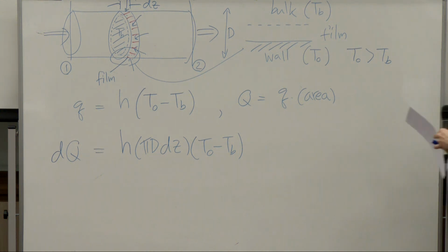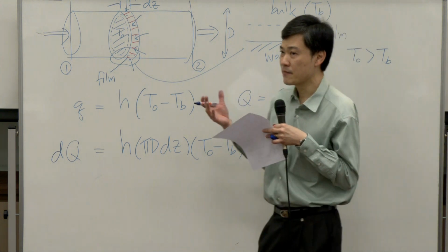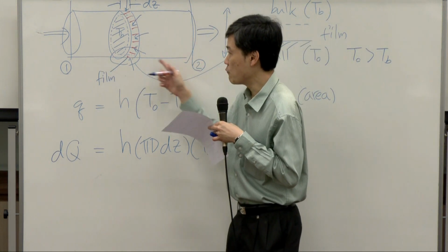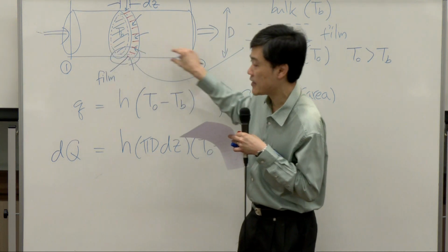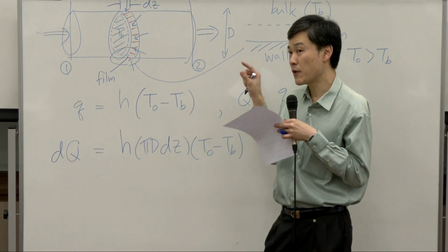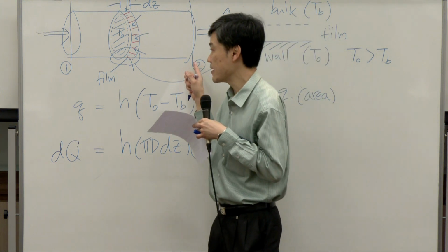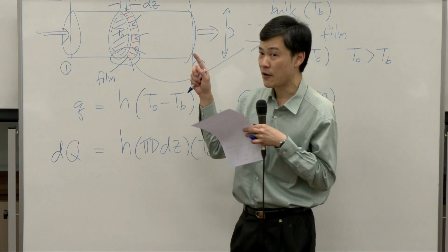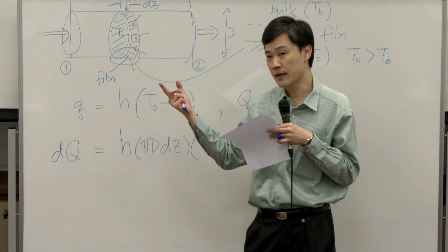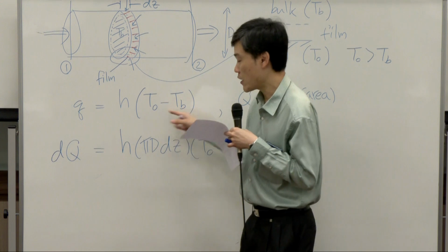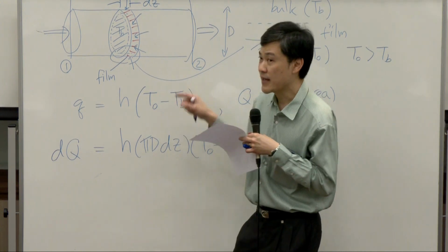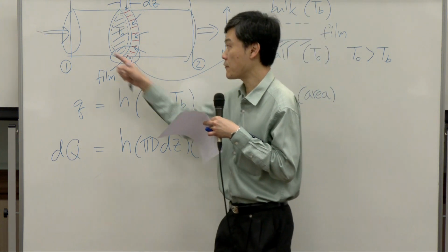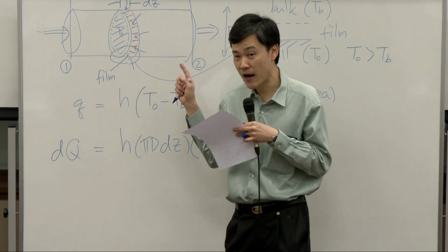But, of course, as I said, my problem is that if you want to do a microscopic balance, we cannot measure temperature at each point. What we prefer is to represent the whole amount of heat transfer for the whole pipe by means of the simple Newton law of cooling. But now the delta T that we are going to use, instead of the exact driving force, is going to use the temperature from the inlet and the outlet somehow.